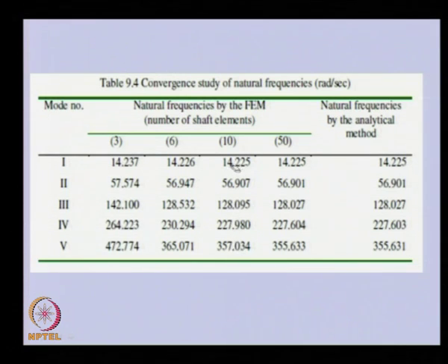So, just to test whether these are accurate, I have taken 50 elements. You can see now that up to the 4th mode, with the 10th element itself, we have got that. There is slight improvement in the 5th mode as compared to the 10th element. So, with 50 elements we could get quite accurate results up to the 5th mode, but let us